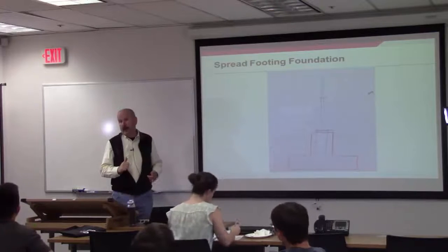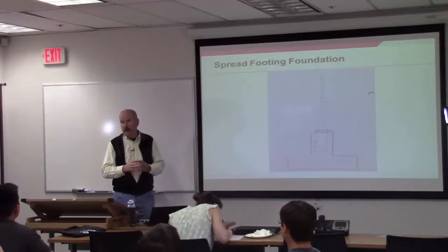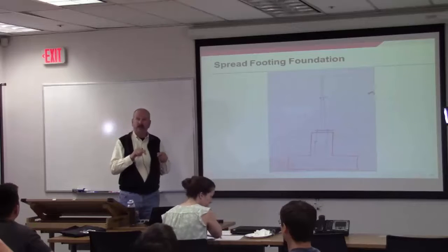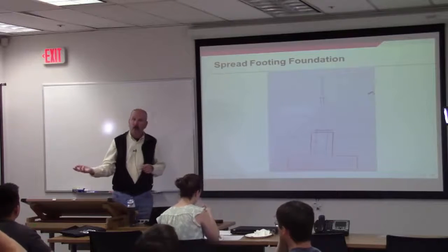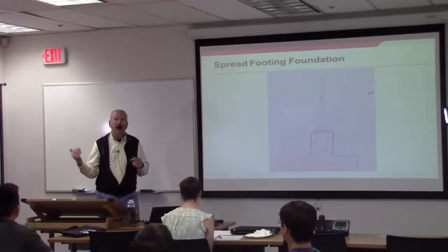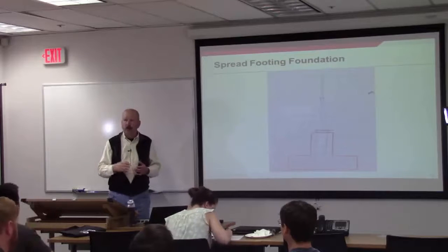One of the things I will tell you, if you have a limited budget or limited attention for your QA check, put your extra effort into foundations as opposed to wiring. I can fix wires in the field. I cannot gracefully fix a foundation that's out of place. Try to use as many standard structures as you can.